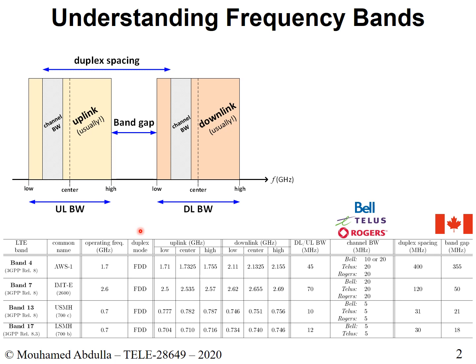You have satellites in outer space, and these satellites are transmitting signals, and you have a phone. In your phone, you have an antenna, a GPS antenna that can detect signals from a satellite. And you need at least 4 satellites to know where you are in 3D in space. So at any time when you're outdoors, mostly you'll be able to detect signals from 4 satellites. And this is also an example of a simplex communication. You can only detect a signal. You cannot send a signal to a satellite. That's simplex.